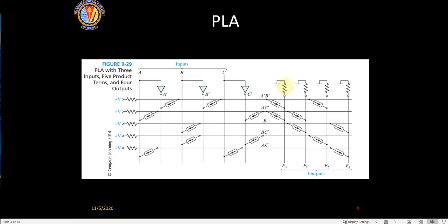So you put a resistance here. This ground connection will ensure that whatever charge was accumulated in the previous state because of these lines being high will find a path to ground. So this will act like a perfect OR. Only when any one of them is high will a high come here. Some current will flow in this resistance, it doesn't matter, because it will not cause any voltage drop, since voltage is coming from here, so it will continue to remain high. Is this aspect clear to all of you?